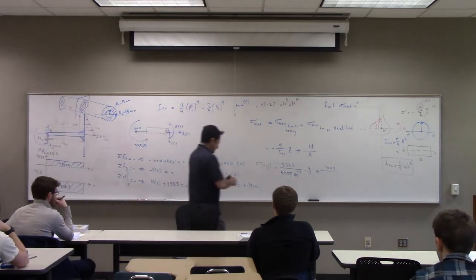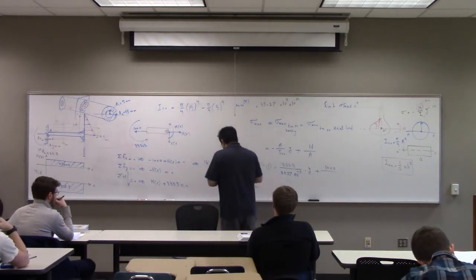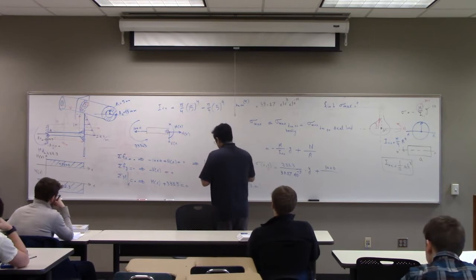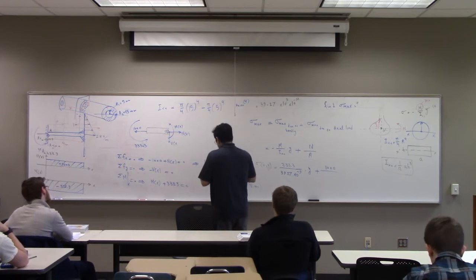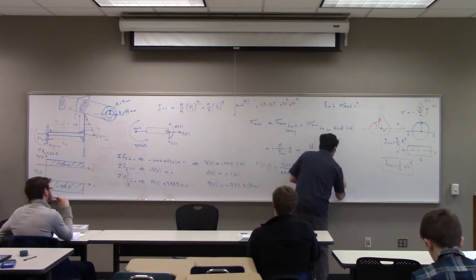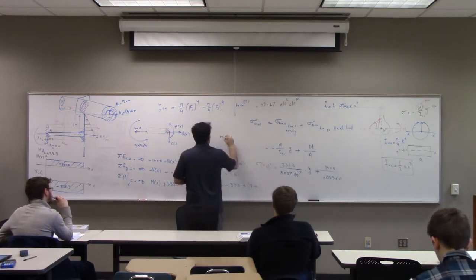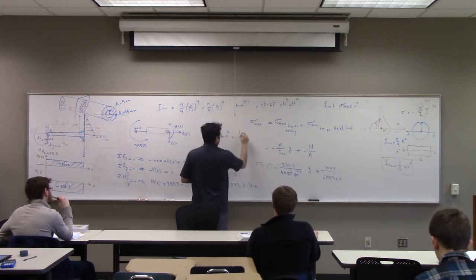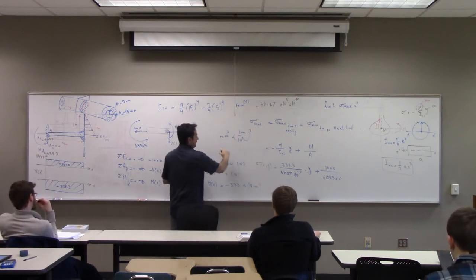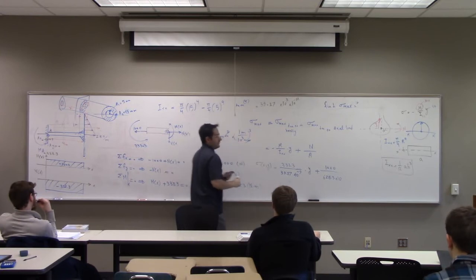So here you have to put pi times the outer, 15 squared minus 5 squared. So it's divided by 628.3, 10 to the negative. This is in millimeters squared. Then you multiply by 1 meter over 10 to the 3 millimeters squared. They cancel out. 10 to the negative 6.